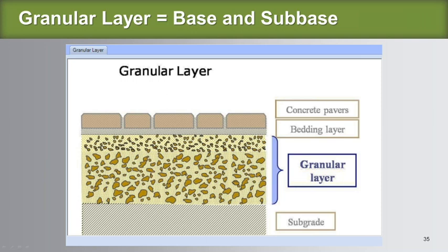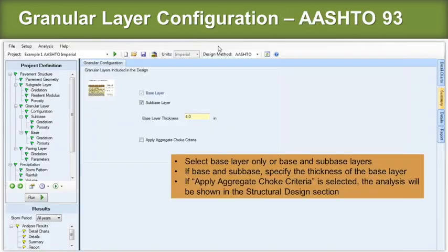Then you go to the larger layers below, which are typically 50, 60, whatever millimeters, so about 2.5 inches in size. And you can't lay that down in a 75 millimeter, 3 inch depth because the aggregate's so big. So we recommend minimums: a minimum of 4 inches, 100 millimeters, of base and a minimum of 150 millimeters, 6 inches, of subbase. We'll talk about that a little more as we move forward. So this is why we have the base thicknesses. This is the default that's populated from the default values you saw in the setup menu. It will default to 4 inches or 100 millimeters, and then you can change it.